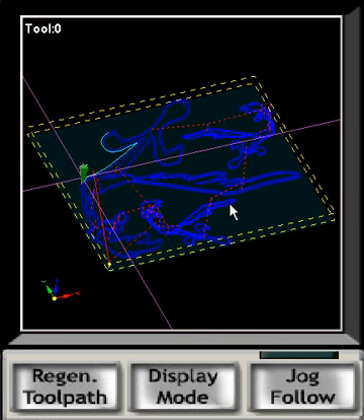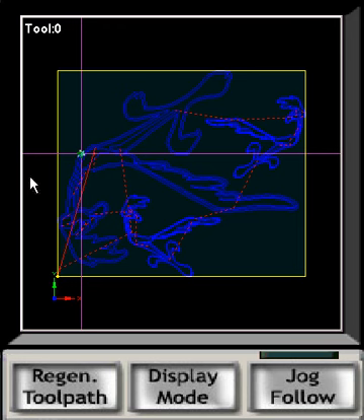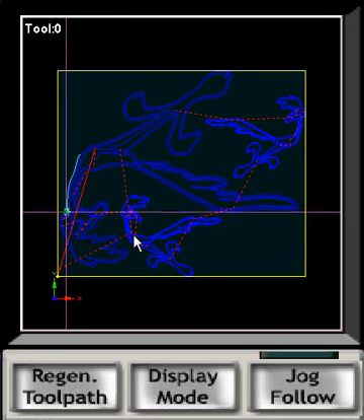One thing you'll notice here is that your eye will be drawn to a movement going on the toolpath screen, and that's because my spindle is on at the moment. And as you can see, the spindle is rotating very slowly. It's actually going at 1/8 speed. If I was to bump my spindle speed now to my maximum pulley speed, you can now see that the spindle is rotating and shows us graphically, even if we're in a top-down view, it's always obvious to you that your spindle is turned on. If I turn off my spindle, you'll see it comes to a stop. Turn my spindle back on and restart my job.